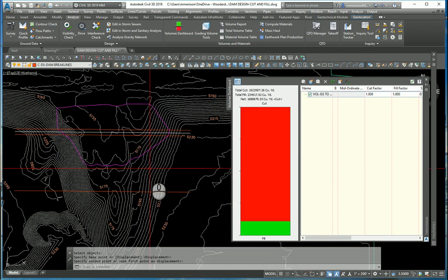And finally he says, you know, I really, really like that. Can you make that a dam? Right now the volume is at 235,000, and he says he's still fine with that. Maybe we want to bring it up a little bit. When you get down close to where he's got the volumes he likes, you can always bring your project up and down. And remember, if you have cuts and fills inside a project, that's great. It's calculating both here for you. Right now, I'm ignoring the cut because I'm only looking for the fill, but it just depends on your project.